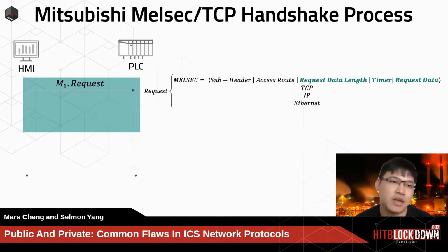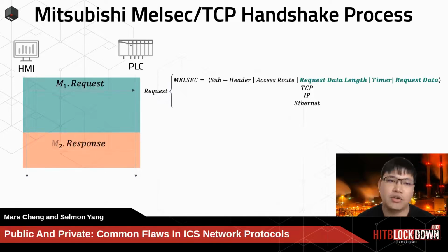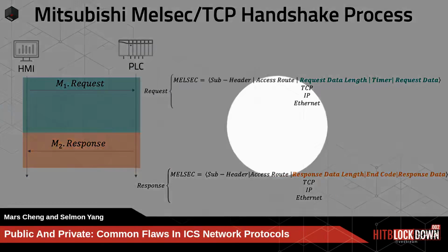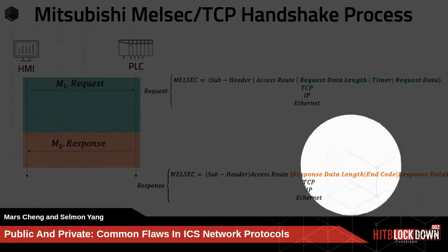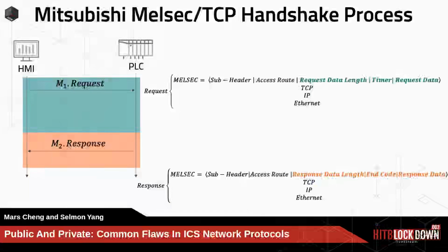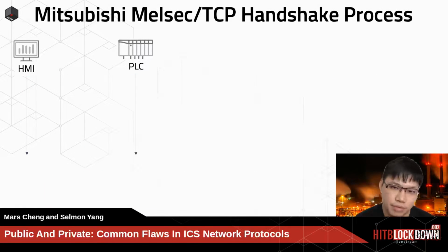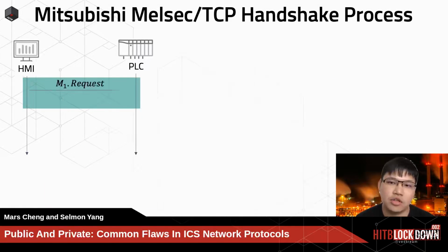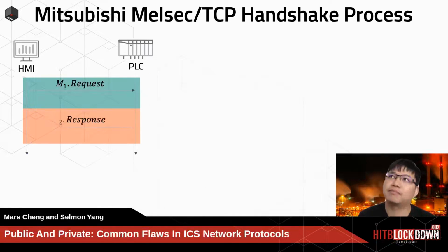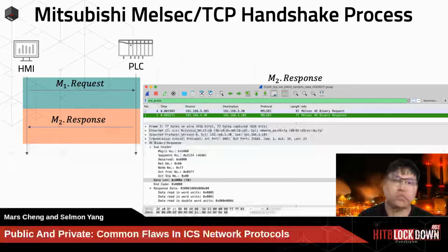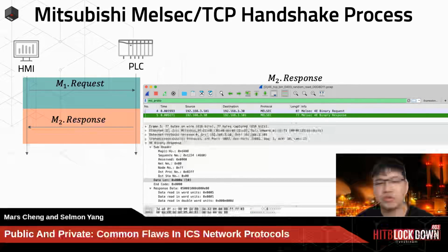Also, there is no TCP handshake; it just sends a request and a response. So here you just need to request the data length and timer request data, and you can try to retrieve it and take over the Mitsubishi MELSEC protocol. There is no authentication and no encryption between the HMI and the PLC. It is a widely used protocol that does not consider any cybersecurity issue.